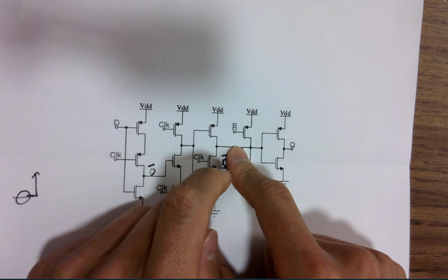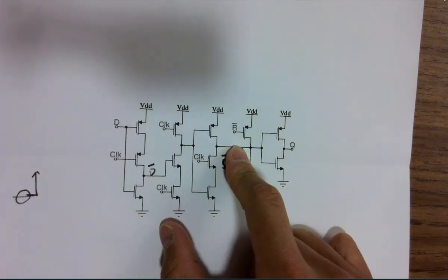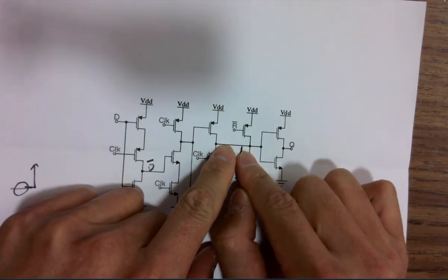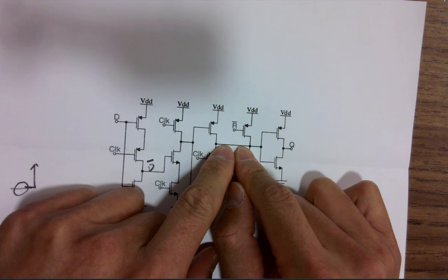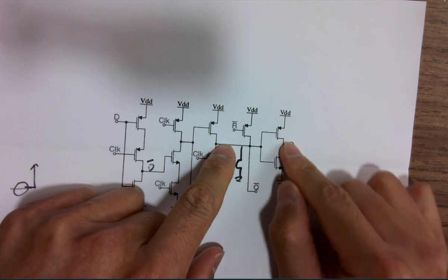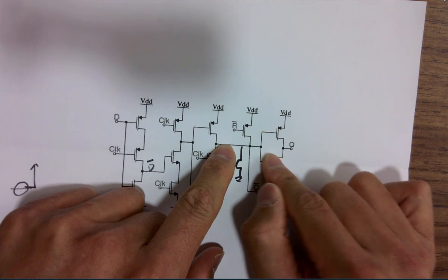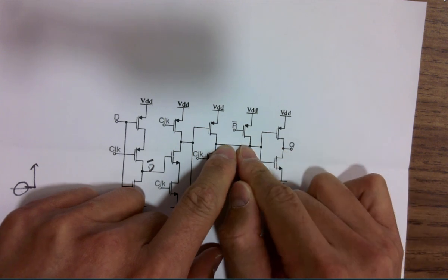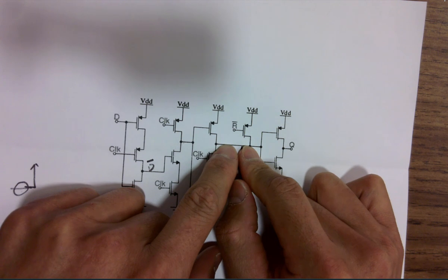It's a memory. It's using all the charges of the gates. All the parasitic capacitors are holding a charge here. It's a floating charge, but it's still a charge. And there's no control after that because it's just an inverter. It's not being clocked. So that charge, that memory, that data, whatever was stored over there will stay.